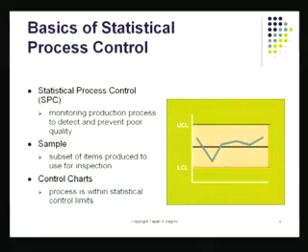What does a chart look like? I have a little plot here. Notice here there is a trace of these statistics. So if this was, for example, I'm jumping the gun a little bit, let's say I plotted X bar, and I'll show you in a minute what X bar is. I plot X bar on the Y axis and time on the X axis. There will be some variation, which is what we call the natural variation of the process.